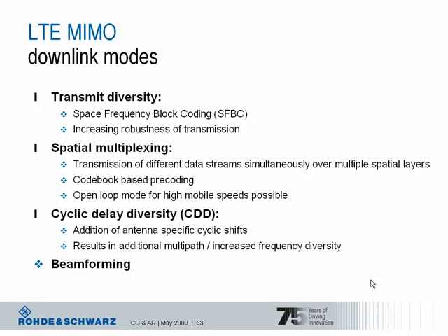An additional scheme used in LTE is called cyclic delay diversity. It is used in addition to spatial multiplexing as a further enhancement. An antenna-specific delay is added to the signal transmitted by each antenna, delaying the signal effectively, and this is done by a cyclic shift of the signal on each antenna. And this effectively results in an artificial multipath situation experienced at the receiver side, causing increased frequency diversity effect. Finally, beamforming can also be applied in LTE as well, which is especially relevant for the TD-LTE part.